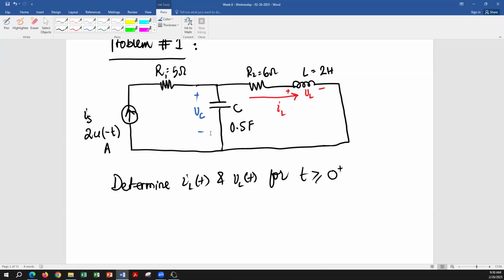And again, in tests and quizzes, you guys still struggle with what is parallel and what is series. That struggle should go away, guys. Parallel: look at the nodes. If components are connected between the same nodes, those components are parallel. If they don't share the same nodes, they cannot be parallel.